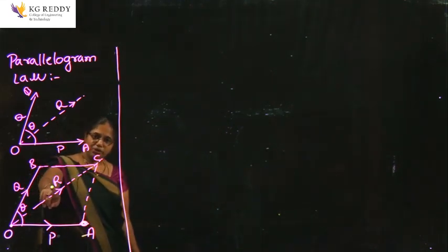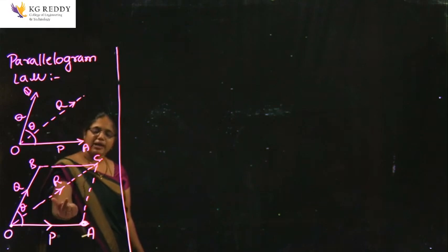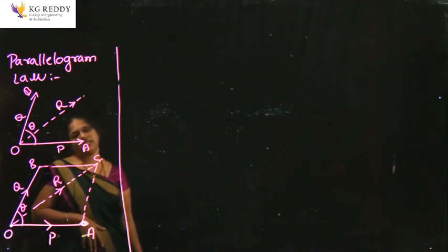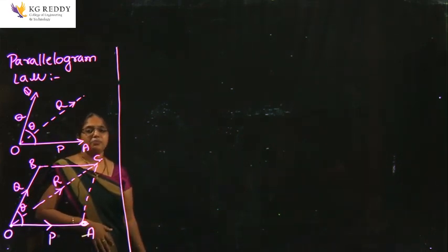Here I am going to find the resultant of the two forces P and Q. Let us take the diagonal of the parallelogram, which has the magnitude and direction. Now, join the lines BC and CA. A parallelogram is formed, which gives the resultant of the two forces P and Q.